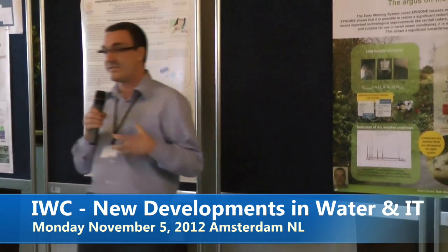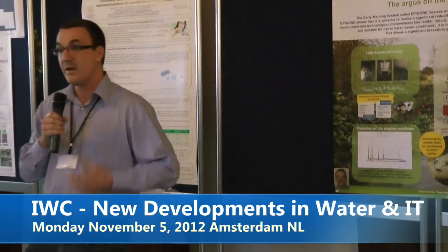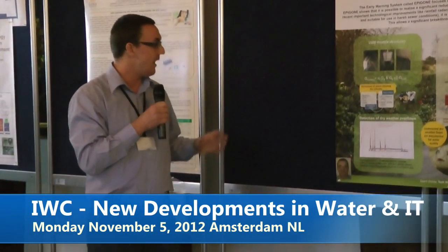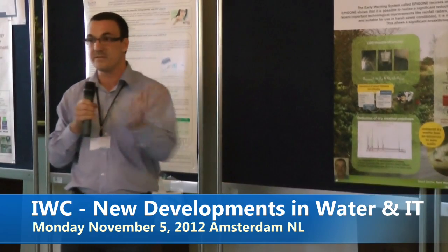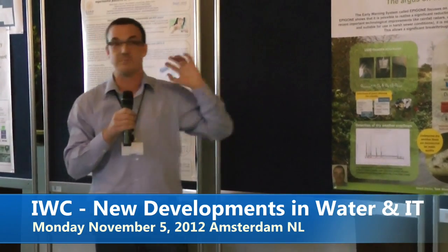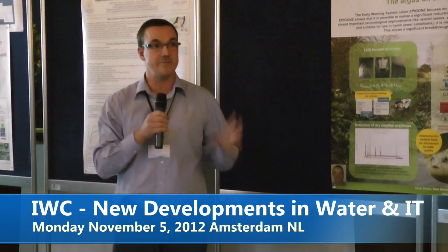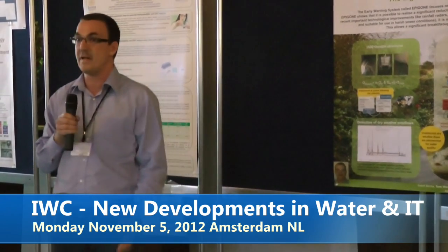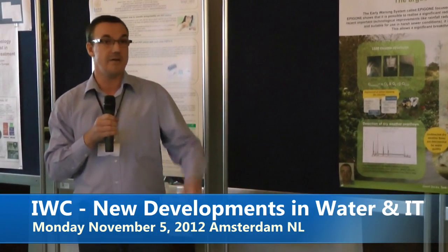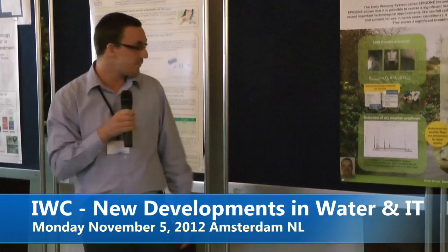These restrictions only happen during rain events and not during dry weather events. During dry weather events, the flow just passes on. During rain events, these structures block the water to prevent overflowing at the wastewater treatment plant or at other streets and so on.